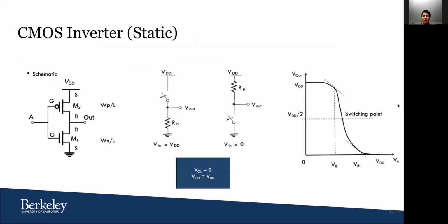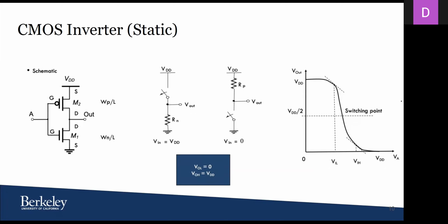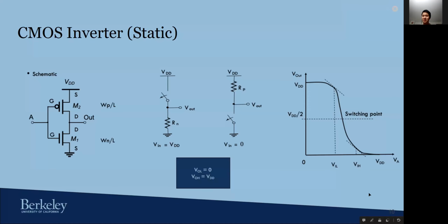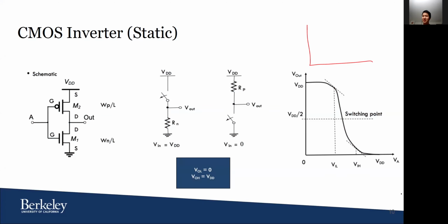All right. Moving on. We need to talk about the static behavior of a CMOS inverter. A CMOS inverter, in the most ideal case, would have a 0 resistance when it is on, pulling high and also pulling low in the other case. So in the very ideal case, you would have a voltage transfer characteristic with V in here and V out here, with a sharp transition.